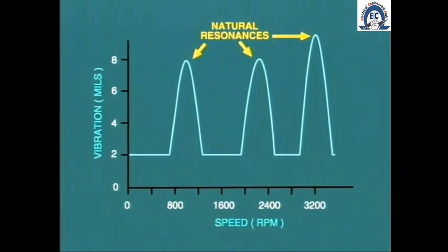If the rotor is allowed to run for any length of time, even a few minutes, at a critical speed, the vibration would be great enough to probably shatter blades and perhaps other components. In order to avoid this situation, we must pass as quickly as possible through the critical speeds during the run-up. But what are these critical speeds?